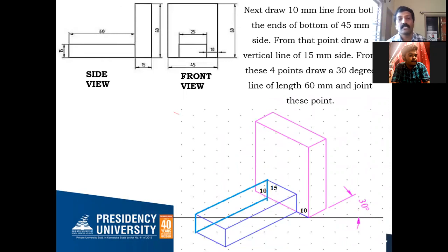So here you can easily see, from this point, all of you listen carefully and observe this cursor also from this point. So you take isometric 10 millimeter, mark this point. Similarly, from here you take isometric 10 and mark this point. Okay, on either side 10, 10 you are leaving it, so that I can place exactly at the center 25 millimeter. So if you measure from here to here this distance, it is 25 isometric scale you are going to get. So after this, what is the thickness of the rectangle here, height?